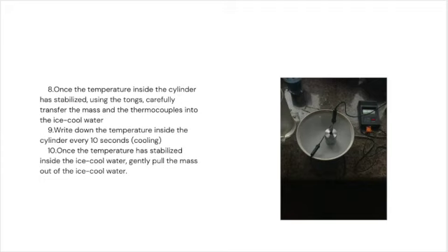Before actually transferring the mass to the cold water, you need to check if the temperature inside the cylinder has stabilized for a certain amount of time. Before it's stabilized, you can't put it into the cold water. Once it's stabilized, carefully use the tongs to transfer the mass and thermocouples simultaneously into the cool water.